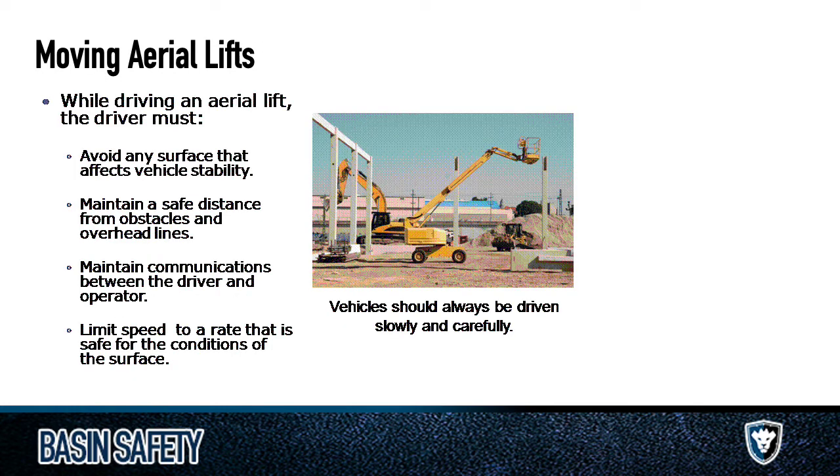Moving aerial lifts. While driving it, you want to make sure that you avoid any surface that affects vehicle stability. Maintain a safe distance from obstacles and especially overhead lines. You want guys on tag lines with the equipment, which we'll get into on the rigging side if you're lifting things.